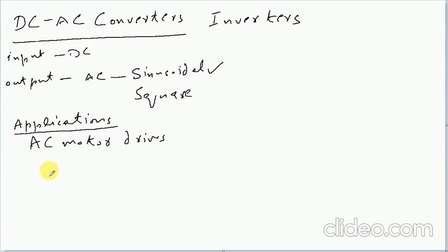We'll also see one block diagram shortly, in which we'll have some input AC voltage from the utility or the grid, and that will be first converted to a DC voltage through a controlled or uncontrolled rectifier, mostly uncontrolled, and then through the inverter circuit it will be converted to AC voltage again. So why is this first conversion and then inversion required?